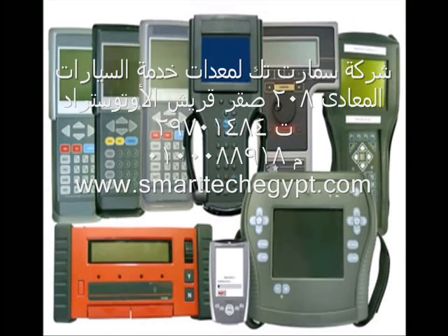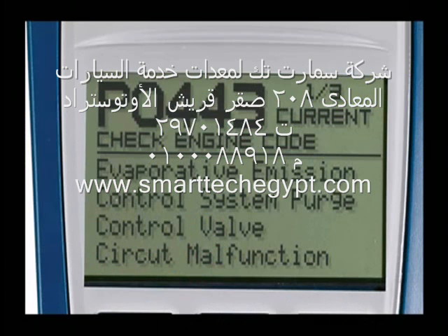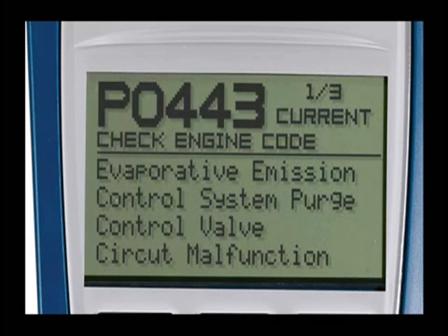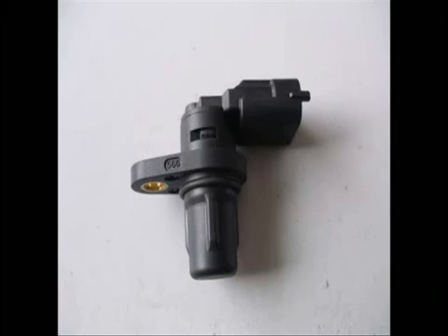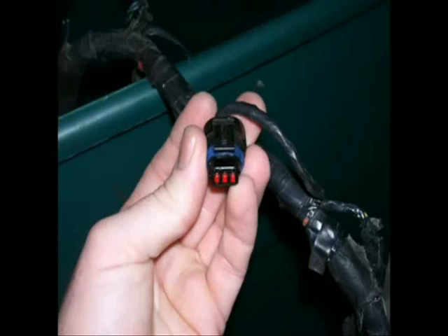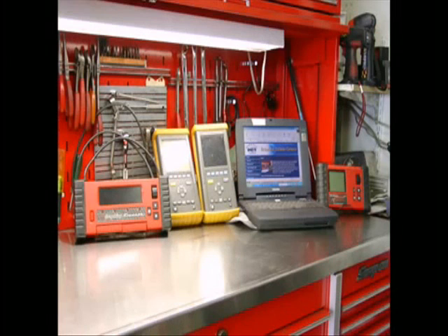We use various diagnostic tools to find the breakdown of cars. Scan tool is a typical diagnostic tool. Unfortunately, what scan tool says is a little bit comprehensive and not detailed. So, a mechanic should figure out using other tools if it's a matter of the part itself or the wire harness connected to the part. To discover the failure of electronic parts, you need to use lab scope.